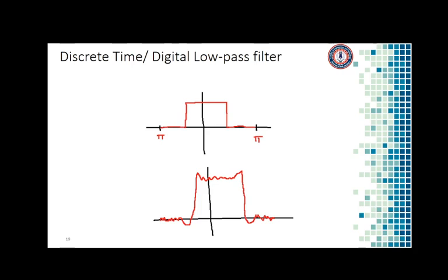So they look something like this, where I say, okay, this is high frequency, for the reason we'll talk about in the next couple of weeks. There is a symmetry around 0 in the frequency response. That means I could have a filter that looks like an ideal low pass filter. And in practice, we are going to talk about how I can obtain this low pass filter with limited gain for a finite impulse response filter. So in practice, the filter which we will design may look funky like this, and you may remember seeing one like this from Signals and Systems. We are going to talk about how we will design such responses, but that's the topic for another day.